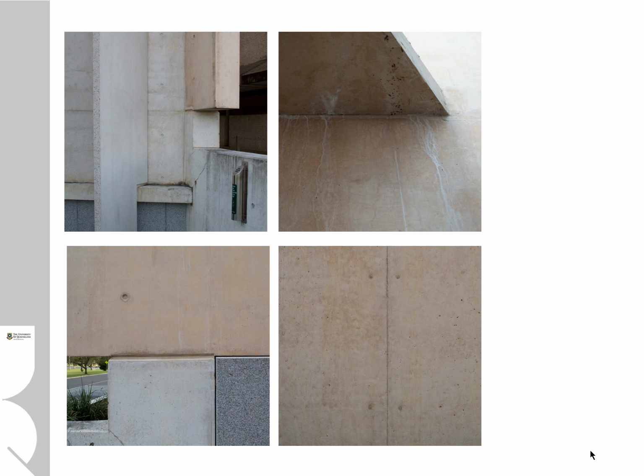And as a result, when the second pour of the roof came on top of it, we're getting a lot of leakage and spoil coming from, I guess, the bleed water from the concrete pour above it, which has then stained the coloured concrete below in an uncontrolled and unsightly way, which is virtually impossible to get rid of.